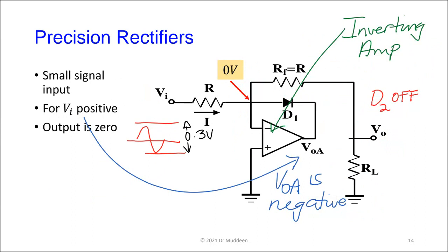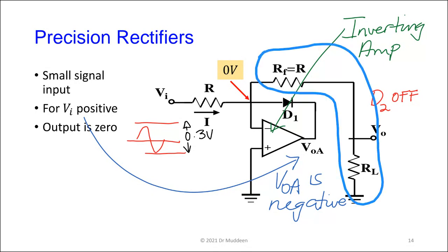When the input here is negative, D2 is out of the circuit, so that the actual output here, this whole thing, basically has nothing flowing through it because you have 0 volts. One side is grounded, the other side is at 0 volts. So it has nothing to do with the 0.7 or whether the diode is conducting. All you do is reverse bias the diode so it's out of the circuit. Same thing with the other one.